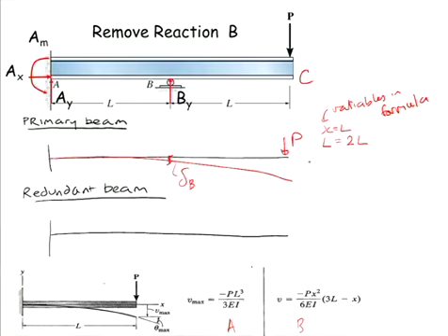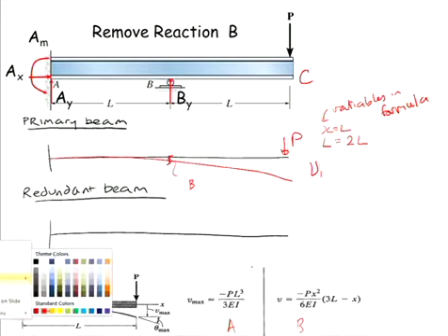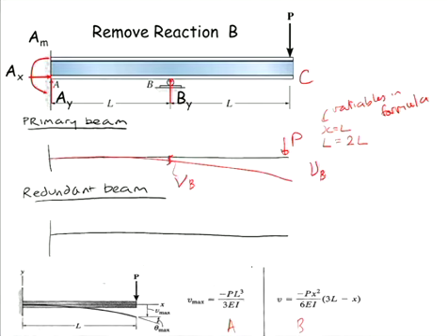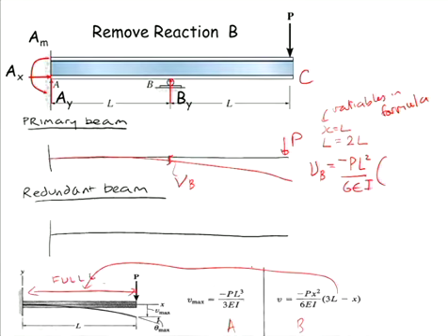So thus, plugging into our formula here, I'll write this as VB. I'll stick to V's. So this is VB. Working out this value VB here, my load is P. I said X is equal to L, so X squared, L squared. And this L value here actually refers to the full length in the formula. But our full length is actually equal to 2L. Thus in here we would write 3 times 2L minus L. So plugging all that in there, you end up with 5 on 6 PL cubed on EI.